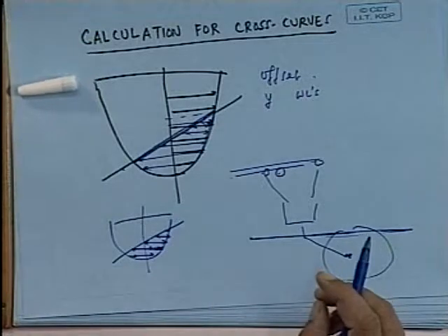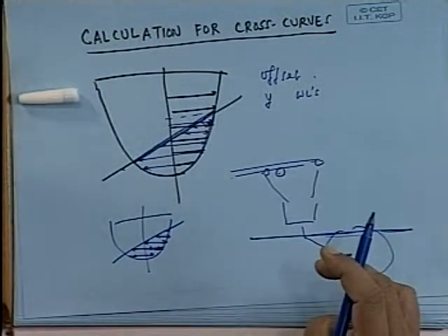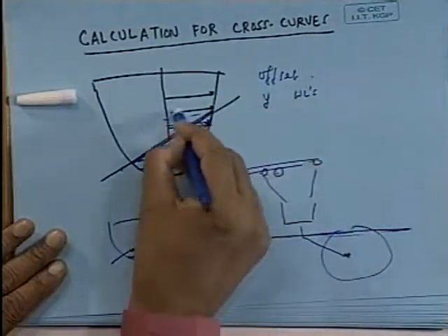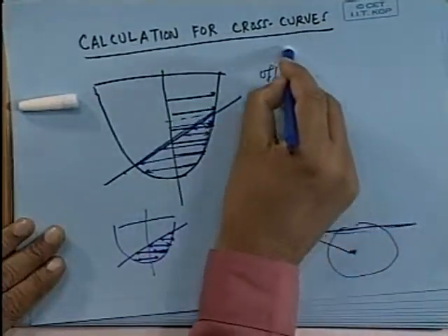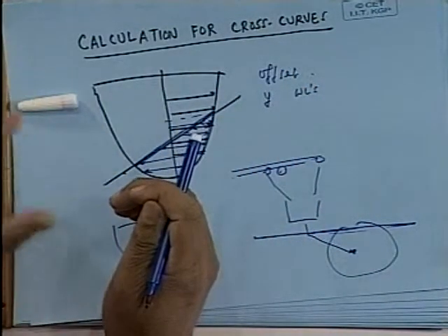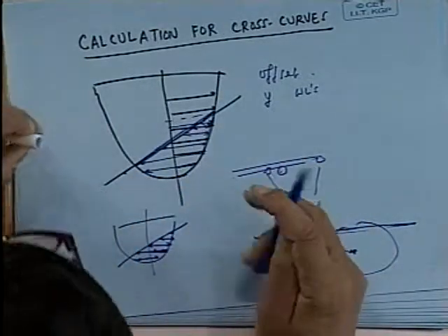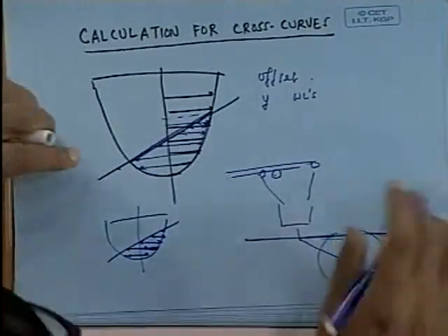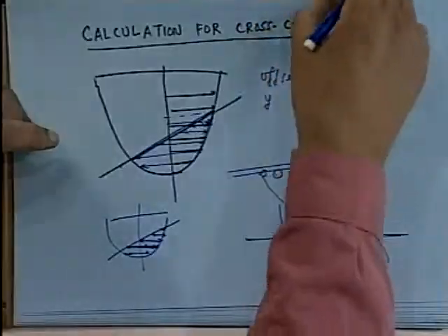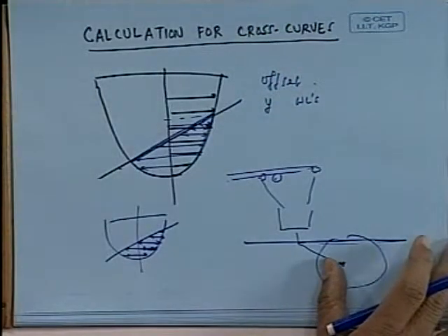So it was a very interesting instrument called an integrator, where you take the knob of the instrument and trace the curve in a cyclic way. It must be a closed curve, and obviously the instrument will move here. There is a gear that would actually turn, and it will give you the area. So this is very interesting. But now the question is, if I do that, I only get the area of a section, but I need the volume. That means even with this instrument, I have to do it for each section, note it down somewhere, then do Simpson's formula. So there should be a better way of doing that.